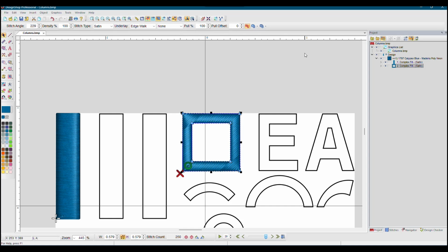Now, of course, depending on whether you have vector or professional, if you have vector, you'll have to manually do it. You'll have to go to here, the stitch line direction, and actually put in the direction. Actually, you know what? I'm going to undo that for a minute. So on vector, you have to manually do this, and you just do the corners. Just draw an imaginary box in the corners, and voila, there you go. So you have to manually do it.